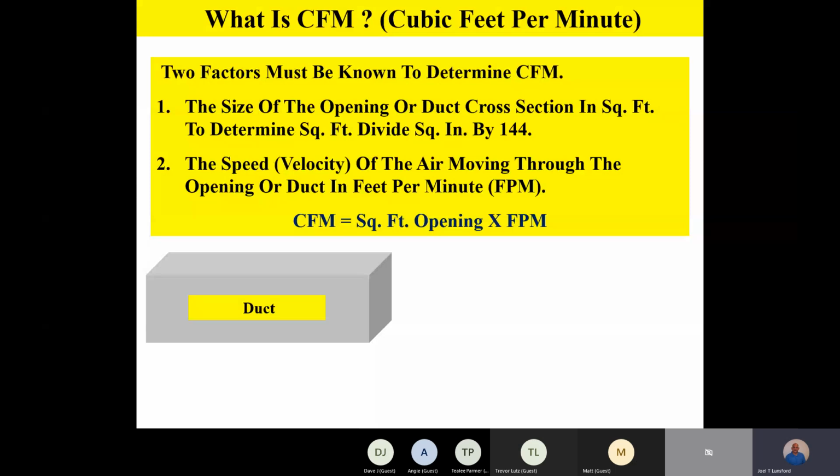In our example, if you take a look at that window on the right, the velocity in feet per minute and the air volume in cubic feet, we see that we have 500 and 500 lined up together as an example. So at 500 CFM, at 500 feet a minute velocity, we need about a 13-inch round duct, or a rectangular equivalent of about a 13 by 11, something like that.